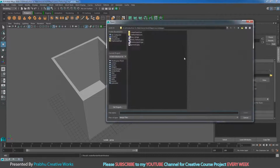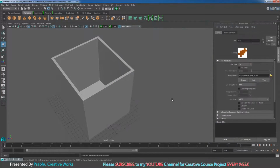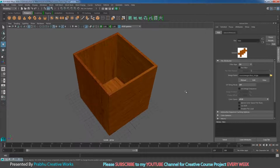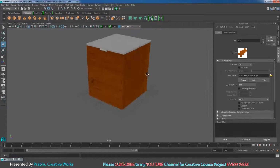So I will click this folder icon and choose box underscore color.tga in your source images and click open. So see here it will be open, but it should not show in viewport. Press 6 key in keyboard to view in texture mode over here. So now it's perfect. Now I want to re-isolate my object like this.